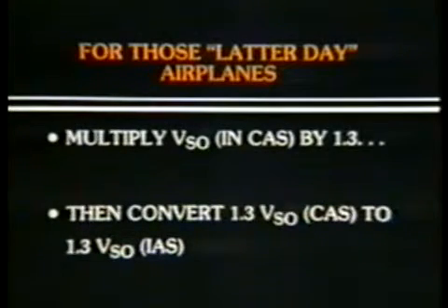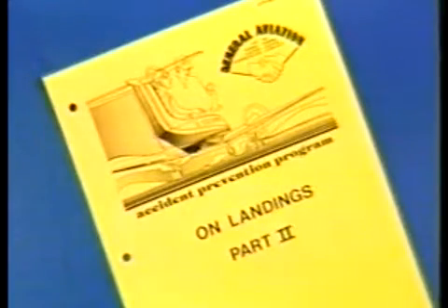To do anything else would create the potential for flying an approach at much too slow an airspeed, because the airspeed instrument error in some aircraft can be significant at the lower speeds. This whole subject is something else that we've put in your handout for a more detailed explanation, along with a rule of thumb formula for calculating approach speeds at reduced landing weights.